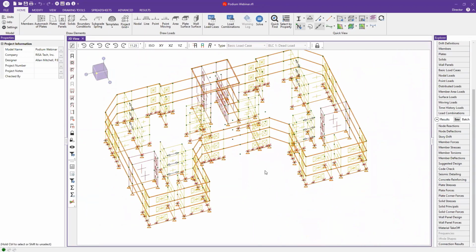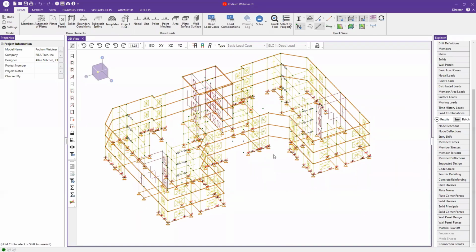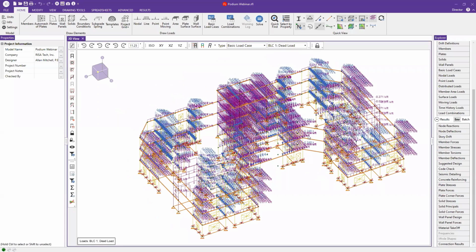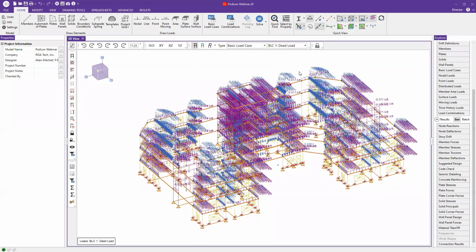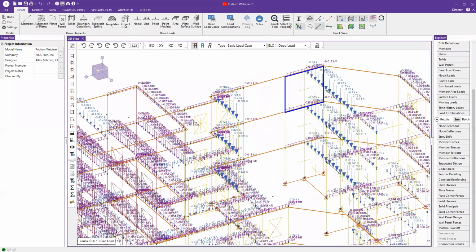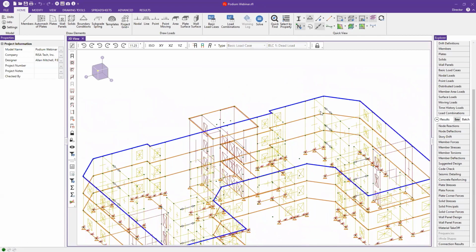And then I have all of the gravity only members in the form of the loading that they apply to this structure. So you can see a lot of loading information came over from this. I haven't entered in any of this myself. It was all automatically generated. And if I flip back and forth between 3D and floor, if I need to go back and make a change, and I come back in here, all of this loading is going to be updated automatically as well. So it's keeping track of all of those loads for you.